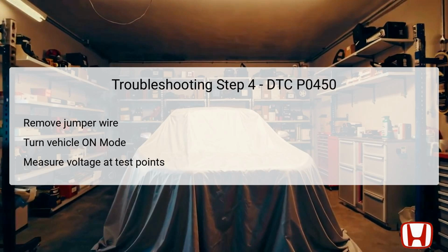With the HDS in hand, measure the voltage between specified test points 1 and 2. Test point 1 is linked to the FTP sensor's female terminal number 1, and test point 2 corresponds to female terminal number 3. The measured voltage should ideally be around 5.0 V. This measurement can reveal whether the wiring and signal pathways are functioning correctly.